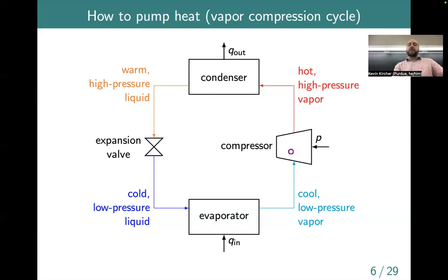So why we need the compressor in the cycle is basically we need to raise the temperature of the working fluid so that it is higher than whatever it is we're trying to keep warm. So you can think of this being indoor environment at maybe 20 Celsius, and outdoor environment, call it, -5 Celsius, something like that. So that -5 C puts an upper limit on how warm the fluid could ever be, right? In order to absorb energy via heat transfer, you need to be in contact with something that's warmer than you are, basically. So in order to get something that is hot enough to give off thermal energy to this 20 Celsius indoor air, we need to raise it to at least a bit above 20 C. And so there is generally something needed in there to do that temperature rise.